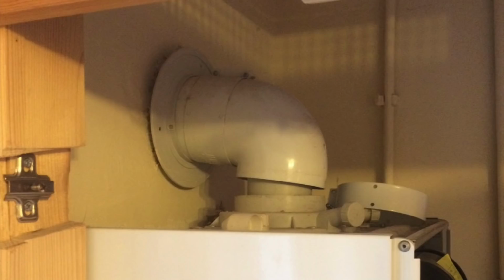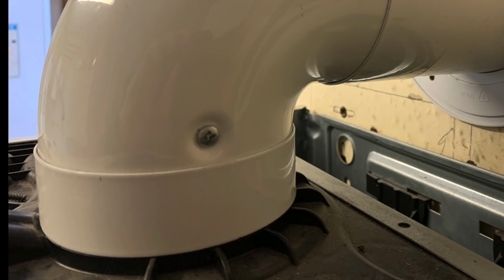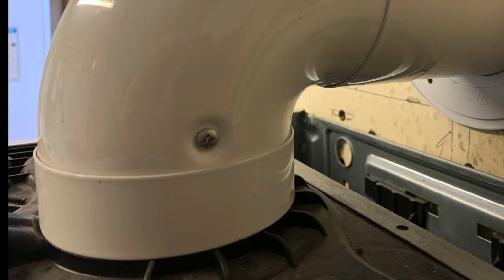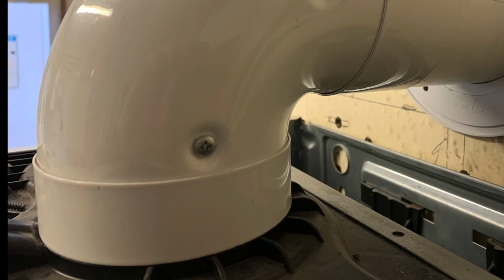So you can see on this Vaillant boiler that these collars can actually hide a poor installation. So you can see this boiler needs to go up at least 3 inches to bring the flue system in line, so the small collar can secure the flue elbow to the actual turret and the elbow itself. The reason why Vaillant want their flue system securing with screws is if the boiler bracket fails, then hopefully the pipework and the flue system will stop the boiler coming crashing down. Hopefully.